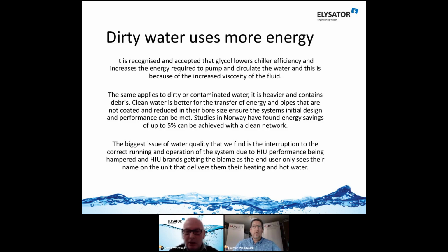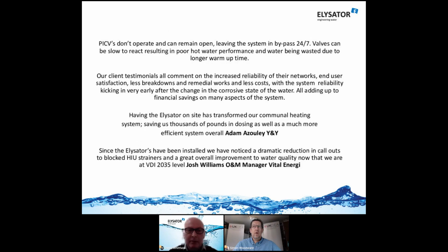Biggest issue of water quality is PICV valves and HIUs. We've done a recent project with Fairheat, where Fairheat took the meter data, and from the meter data themselves, they could see that most of the HIUs were in bypass because the valves have been corroded to such an extent that they weren't closing. A couple of references there from clients where we've saved money on dosing, as well as a much more efficient system overall, because things aren't going wrong.